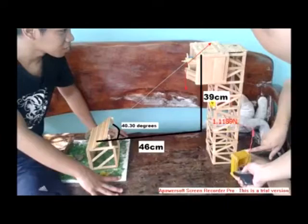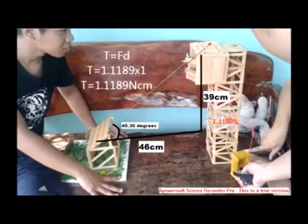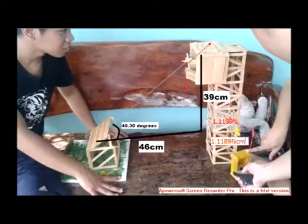For the torque, we just multiply this force by the distance from the shaft. The radius of the shaft of our DC motor is 1 centimeter. Therefore, we could say that the torque is equal to this value multiplied by 1 centimeter, and therefore we could get a value of 1.1189 Newton centimeter. There you have it.